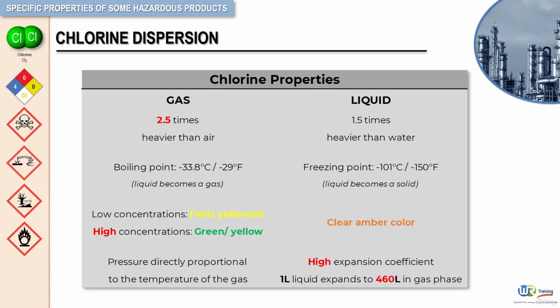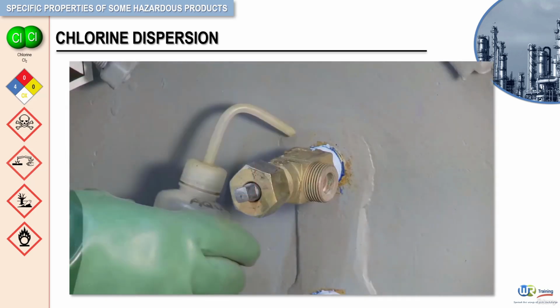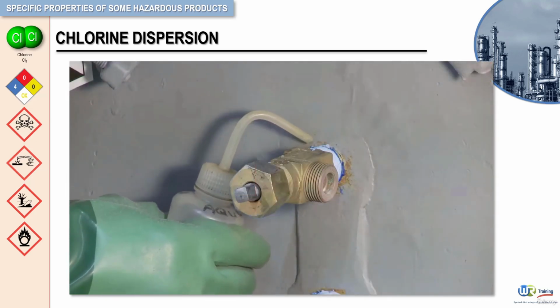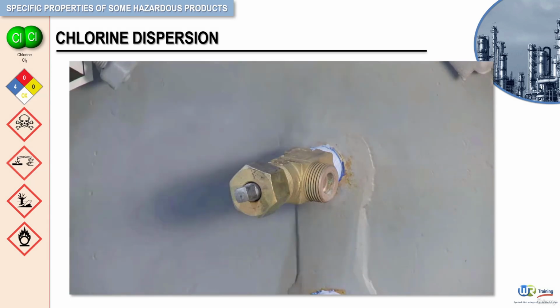Chlorine will be present in transportation containers and at chlorine production, storage, repack, and consumer facilities. Due to the properties of chlorine, most likely the only form of chlorine that a responder will encounter during a release is a gas. Exposure to liquid chlorine will be unlikely unless it occurs at the exact release point. The most common types of chlorine releases are from minor valve leaks that are easily mitigated and have minimal dispersion and ecological effects.